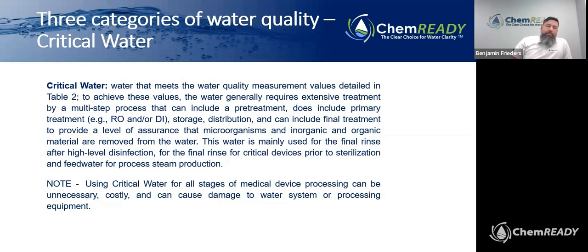So when we talk critical water, we're talking the entire process from start to finish, pre-treatment all the way to the final endotoxin and bacteria treatment. That final product water is called critical water. And this is the only water quality that is acceptable for the final rinse after a high level disinfection.